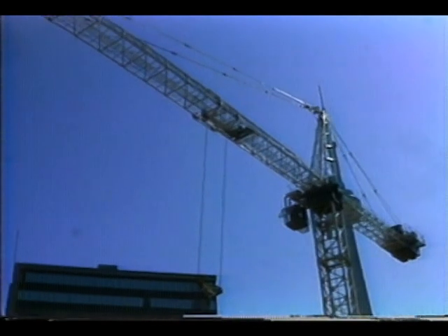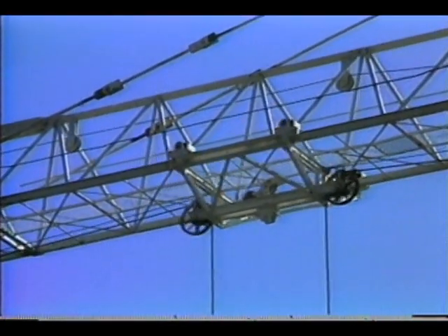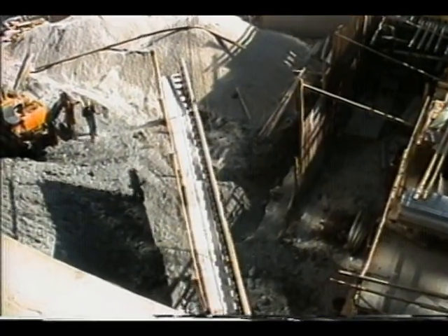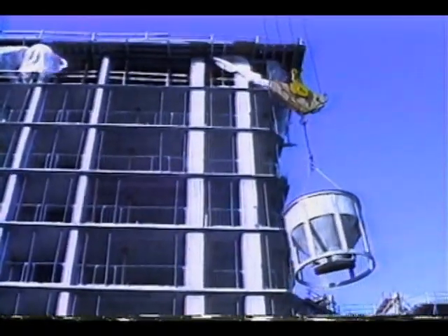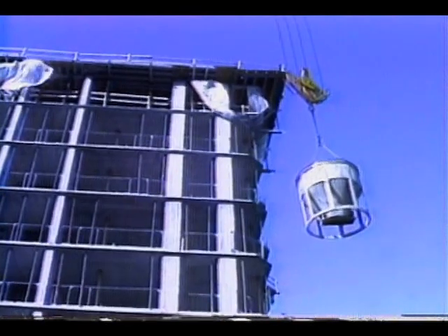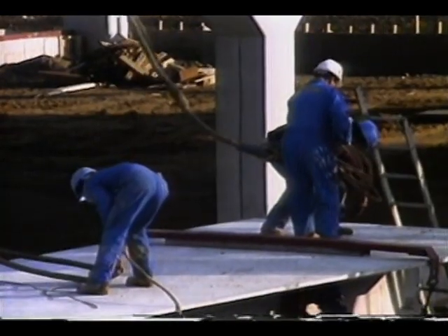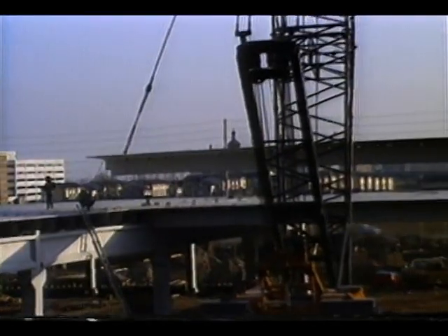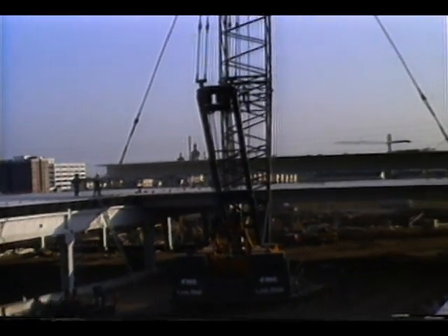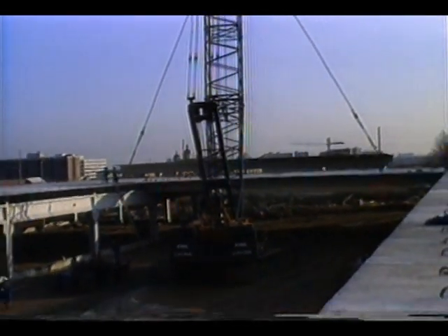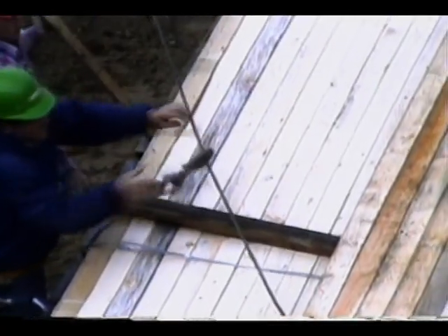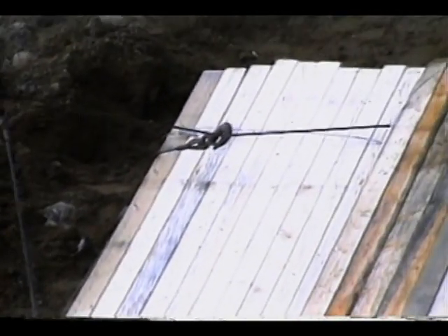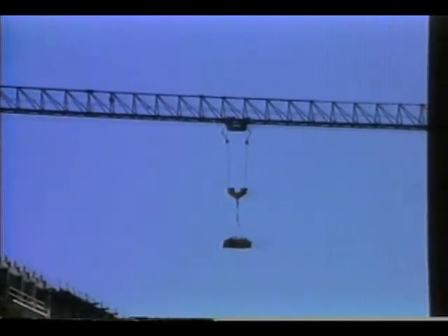There are many factors to be considered in the choice and use of wire rope for rigging and hoisting. One of the most important is safety. Although you must select equipment that will get the job done economically, you must also eliminate any hazard to people and property. Use only wire ropes of the size, grade, and construction specified by the manufacturers of hoisting equipment or wire rope. They base their recommendations on actual working conditions.